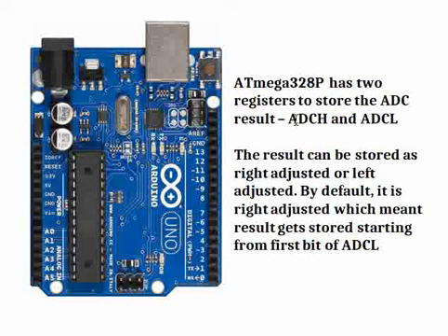So this is another very, very important thing. We have ADC registers where you can configure the result storage as either right adjusted or left adjusted. That's another important point we need to know about reading the ADC.